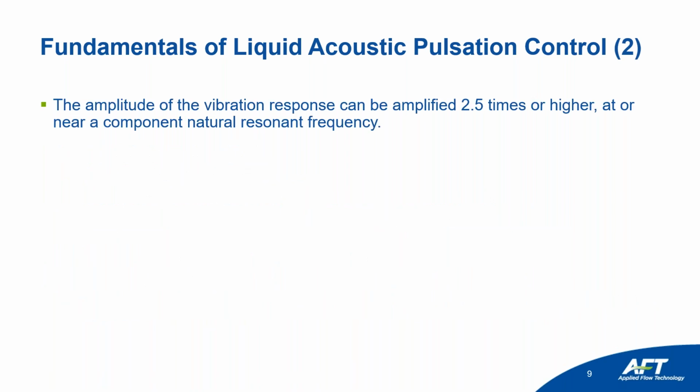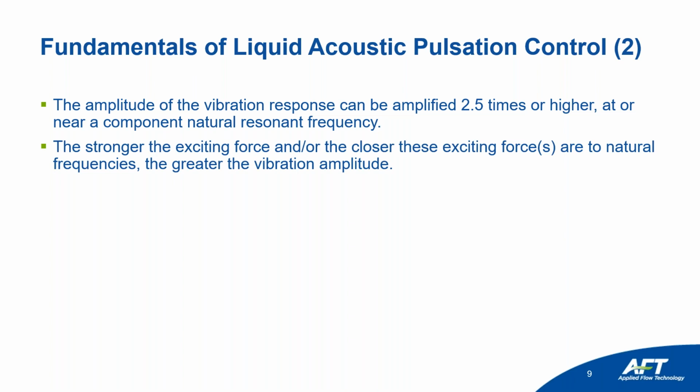The amplitude of the vibration response can be amplified 2.5 times or higher at or near a component natural frequency, or resonant frequency. The stronger the exciting force and/or the closer this exciting force is to natural frequencies, the greater the vibration amplitude will be.